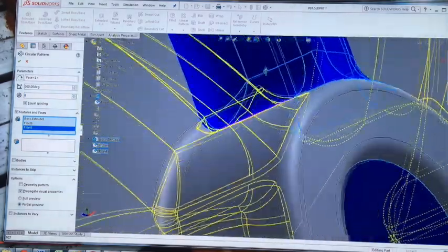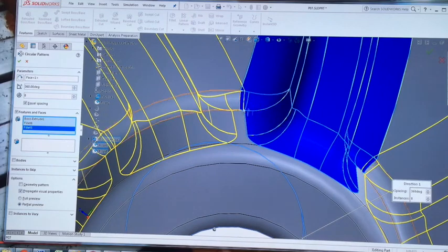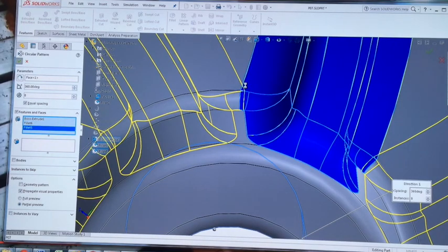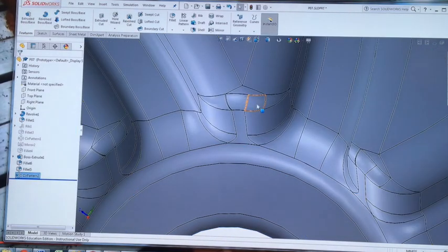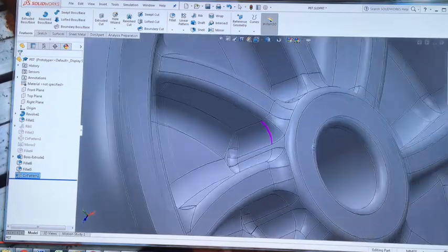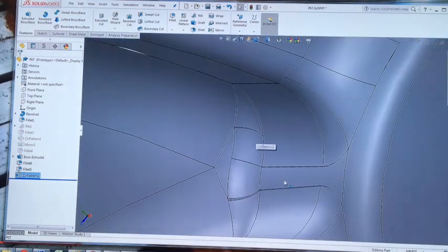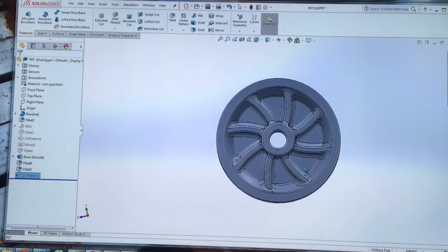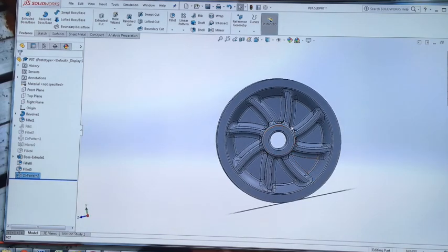Now when you're doing that pattern, you have to be careful that your fillets aren't overlapping. So when I get something like this here, that may prevent me from completing that pattern. We'll see. That's worked okay. It's a little bit messy, but that's okay. Alright. So you can try something like that out as well.